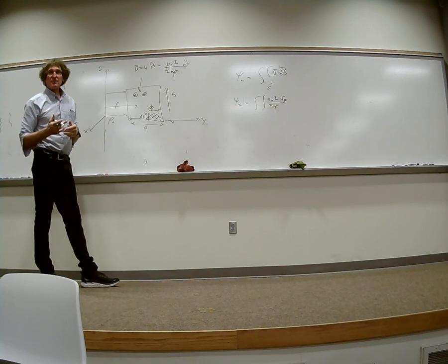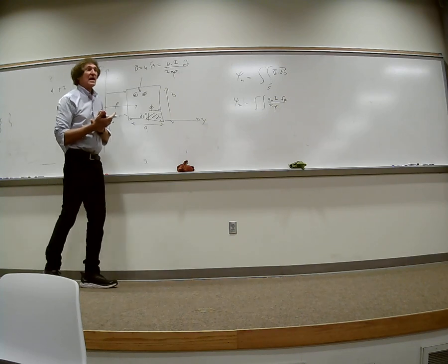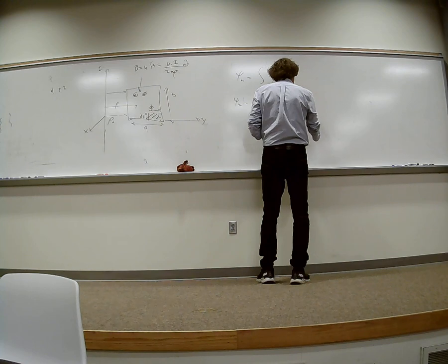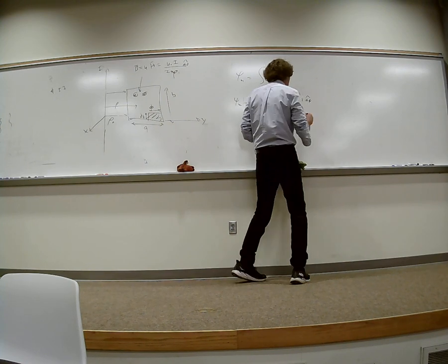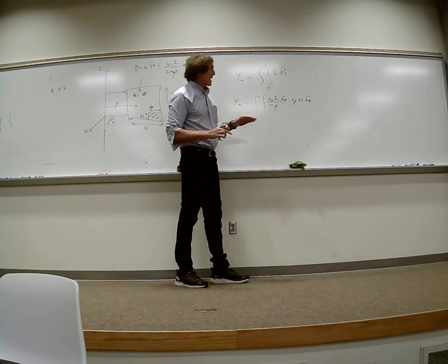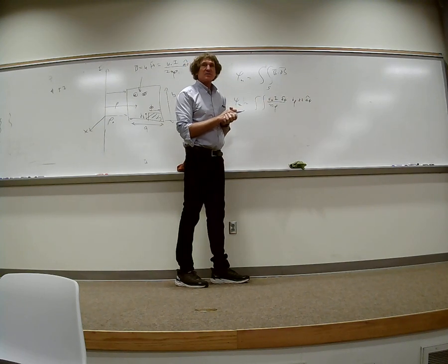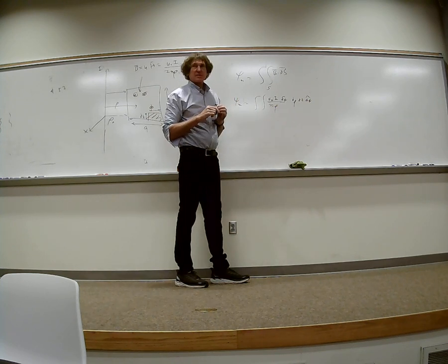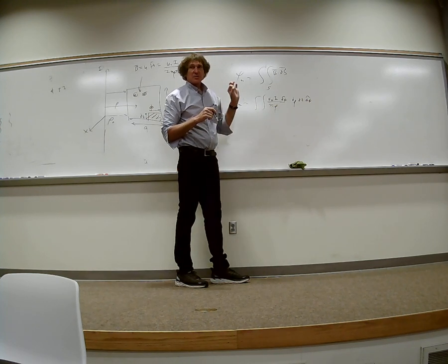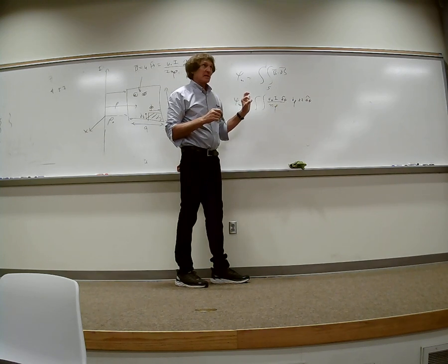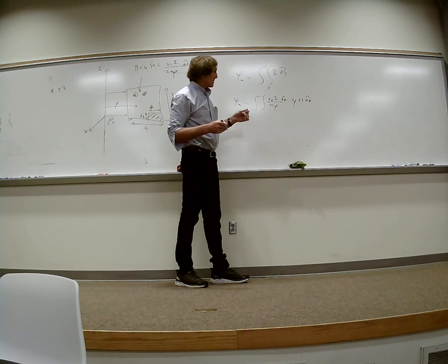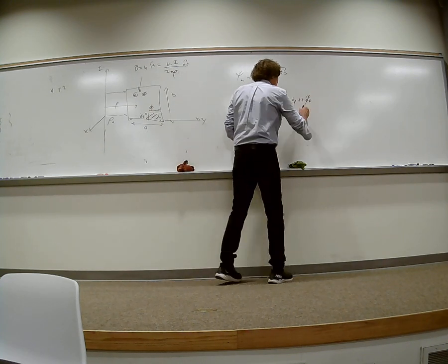The differential surface would have dimension d rho dz, correct? And it's going to be in the A phi direction. Typically on a problem like this, I would make these either AX or AY, but it doesn't matter for this one because the flux is azimuthal, and the surface area will be perpendicular to the actual flux, the penetrating part. So A phi dot A phi is going to be 1 if you dot that out.